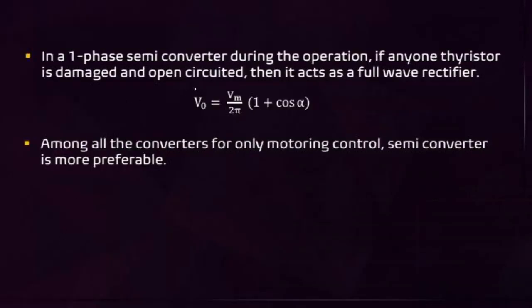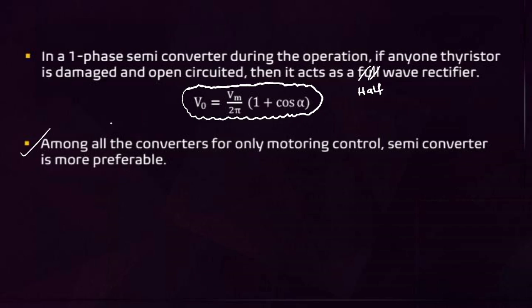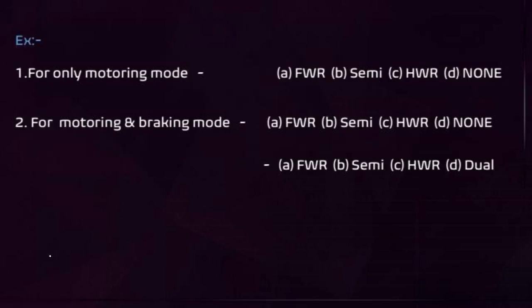I told you already, in a single phase semi-converter, during the operation, if any one thyristor is damaged and open circuited, then it acts as a half wave rectifier, not a full wave rectifier. Among all the converters, for only motoring control, the semi-converter is more preferable.